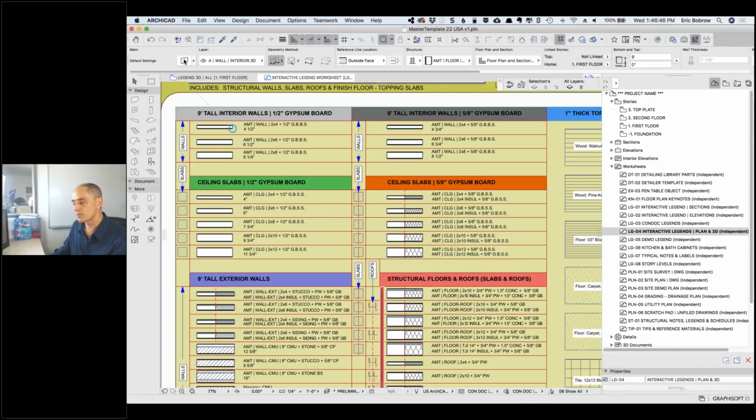So it is, you see it's picked up the settings. It won't show that I've got the wall tool, but it did pick up the settings of this interior wall that I was working on here. I guess this should be an exterior wall if I do this. Yeah, you can see it picked up the exterior. So basically you can eyedrop through the reference.